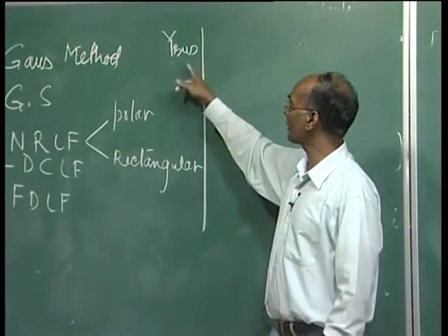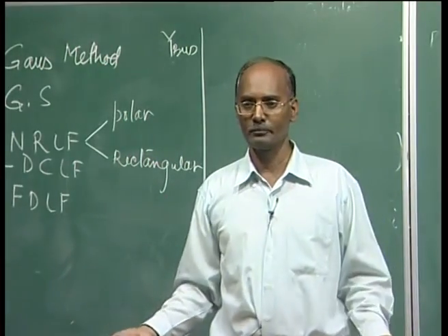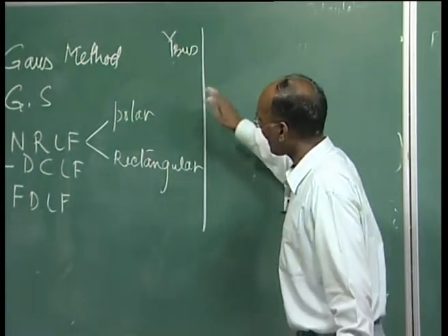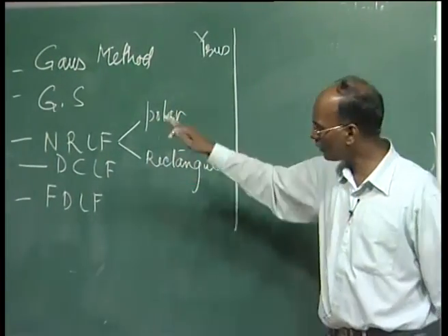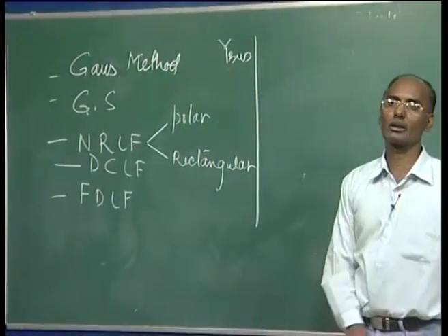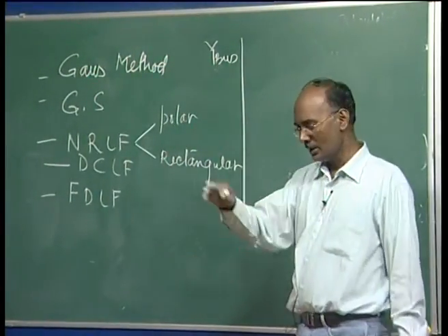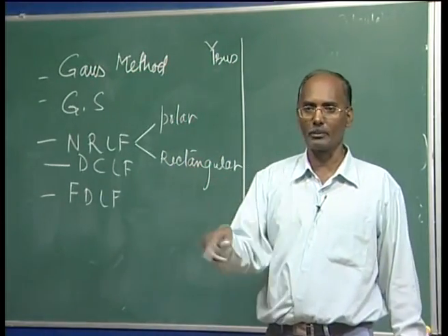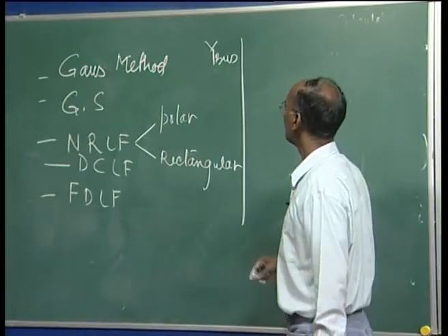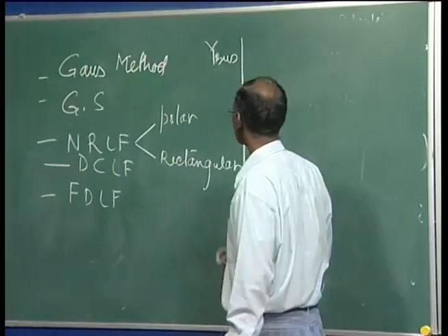But if you are going for the Z bus, it is a full matrix, and that is why it is not sparse. So from the beginning we started with the Y bus, and all the load flow methods are basically running on the Y bus. So we form the Y bus. There are different approaches: whether you are connecting a line or a transformer, your Y bus keeps on being modified, and then you get the complete one. So there are different techniques, different ways, to form it.